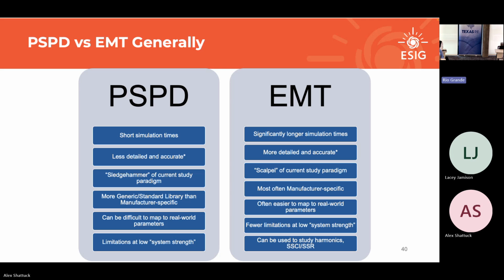The example I like to use is we're doing a study with a regular laptop, like a 4 or 8 core laptop, so I guess a good laptop. And we were running a partially equivalent IBR plant, so one wind farm equivalized to 11 machines, and a 30-second run took about 28 hours.